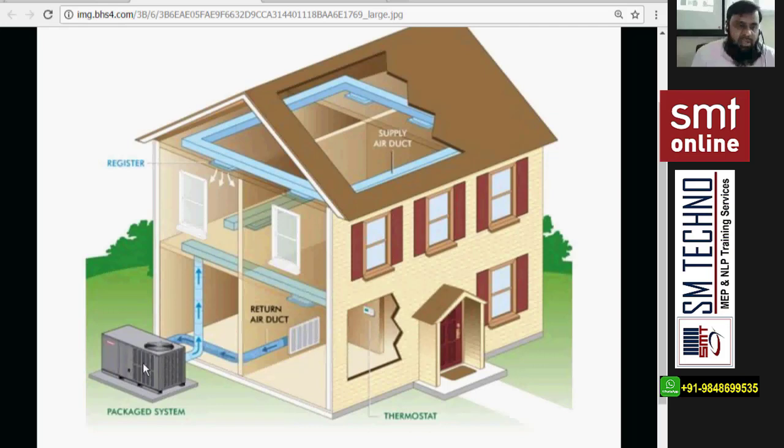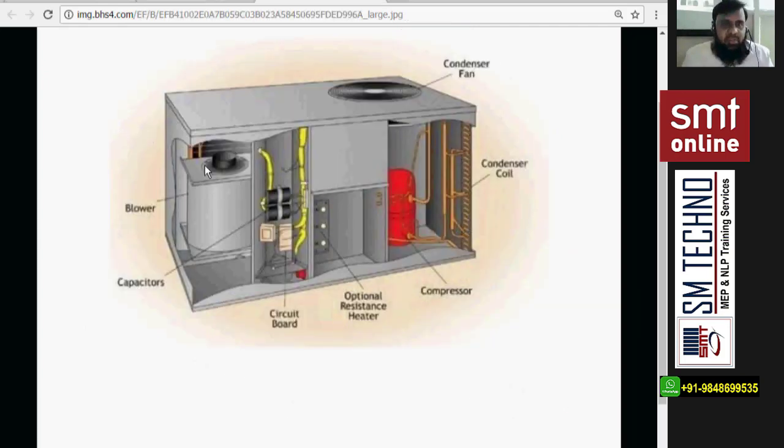So two sections, and the left side section with the evaporator will have a double skin. Double skin means one unit, one case, two cases with insulation in between. This side has insulation. Why? Because this is placed outside now. If you don't provide insulation for this side, the cooling will be lost, right? But there is no insulation on the right section, because this is the compressor and condenser.